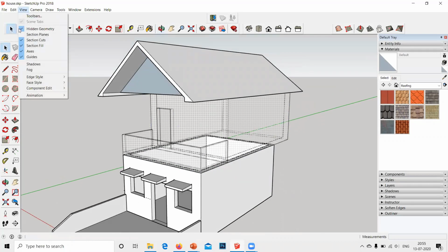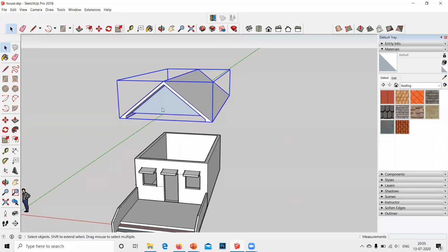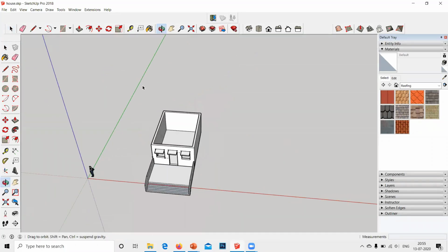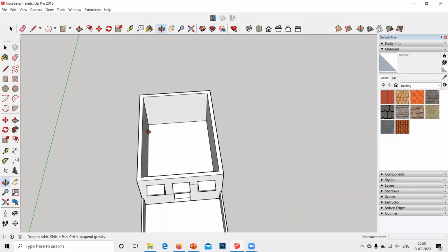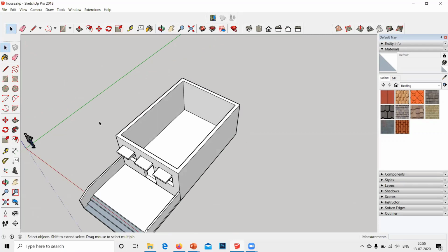I hope this is not very tough. Uncheck hidden geometry. Okay, this is a tough portion. Do the same thing with your roof. Hide. With your move tool, select this endpoint. Now we are having only our stair. Press Control once. We have copied it. So now we are going to move your cursor towards this staircase, where we are going to paste it. Okay, so simple.